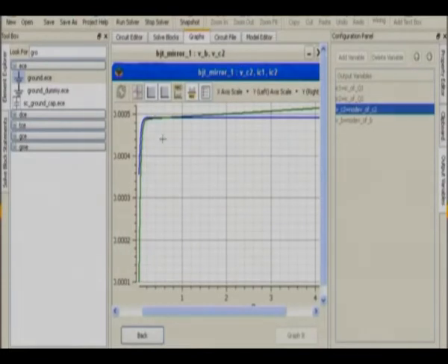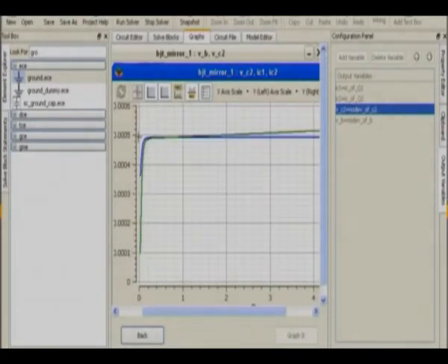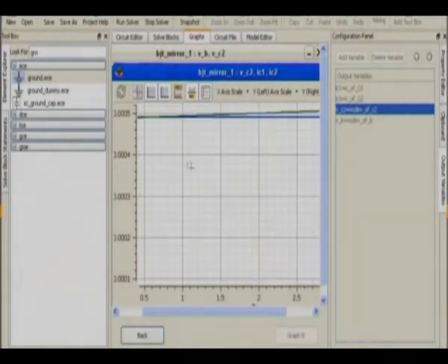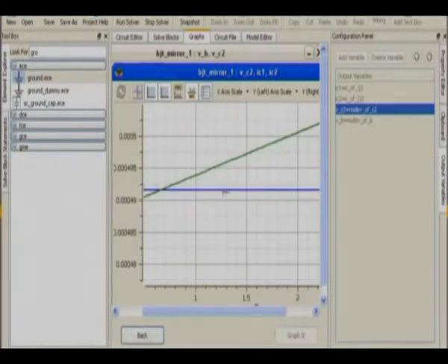Okay. So in this first part, the transistor is in saturation, and we don't operate in that region, so we can actually ignore that part. We should focus on this particular part, and you can see that the output current is not quite constant. This is the input current, and the output current actually varies with the output voltage.